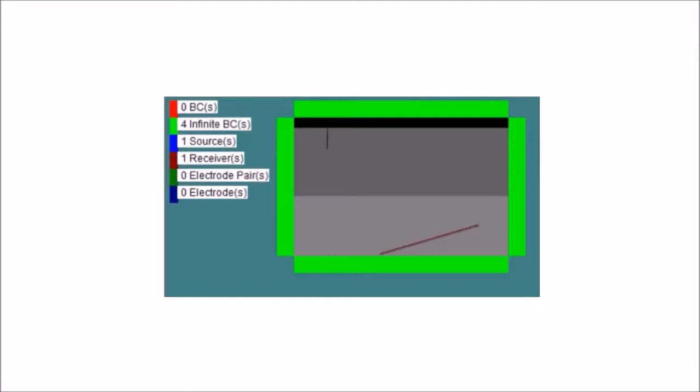The figure shows a 2 mm long vertical crack in the steel wall of the pipe. An ultrasound transducer is placed in the petroleum, working in pulse echo mode. For comparison purposes, the same model as the one just described, but without the crack, is also simulated.